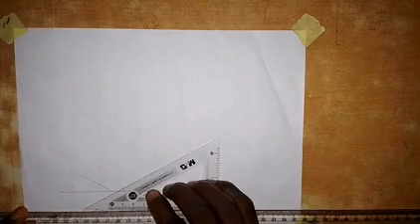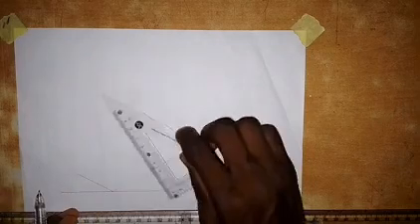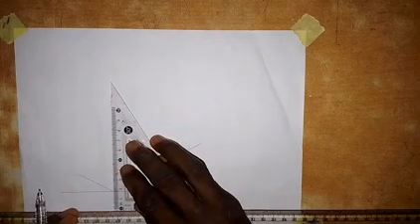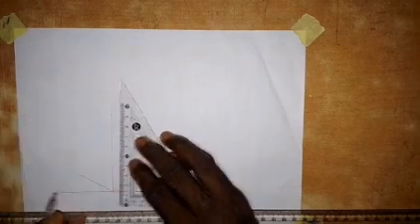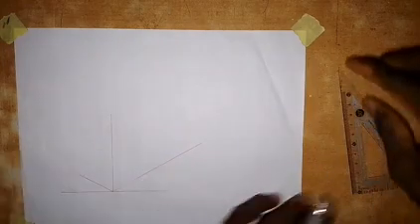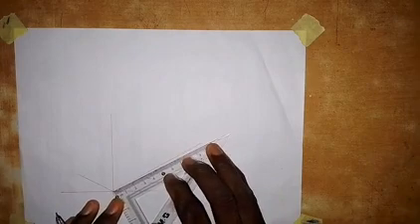And though we are not given the lowest point, I'm going to place it myself. So on this side, I'm going to draw this line in this direction, and then I will turn my set square like this and draw this line in this direction. Alright, and then I'm going to draw a vertical line from this point up like this, and then I'll be taking the measurements right now. So I'm going to take 60 millimeters on this side here.